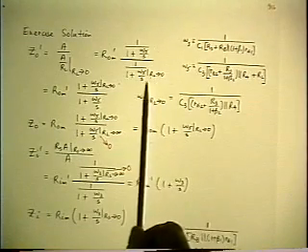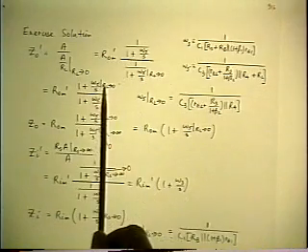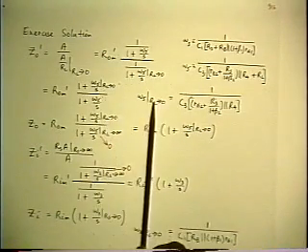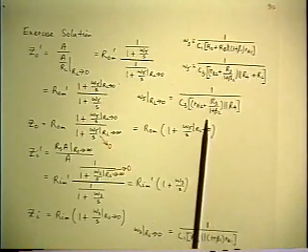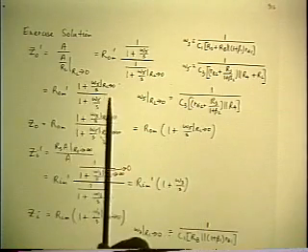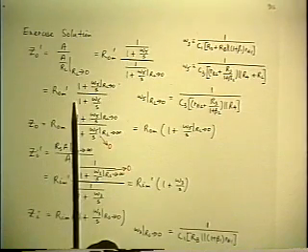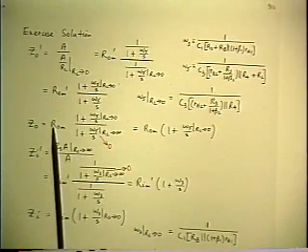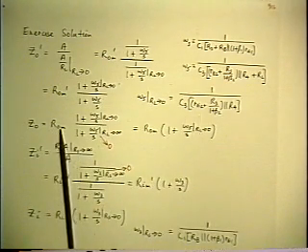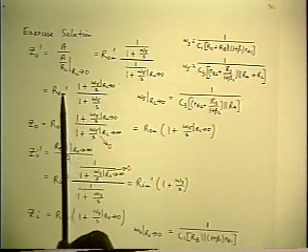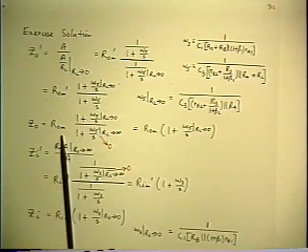All that happens is you define a new corner frequency. This factor from the bottom comes around on top, and it simply is a new corner frequency obtained from the old one by letting RL go to 0. And that's the result, automatically in factored pole zero form. That's for the outside output impedance. If you want the inside output impedance, you take the other limit in the result. So you simply let RL go to infinity in what you have already. So that converts ROM prime to ROM. We've already done it before. You don't have to do it again.